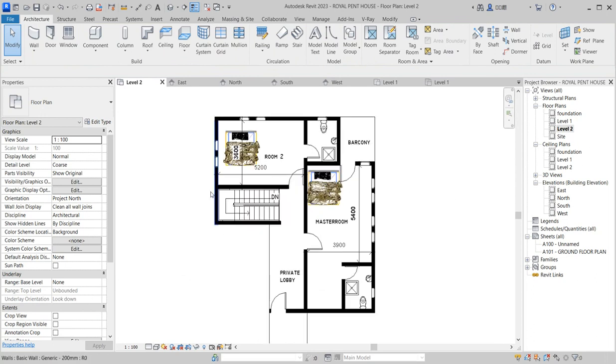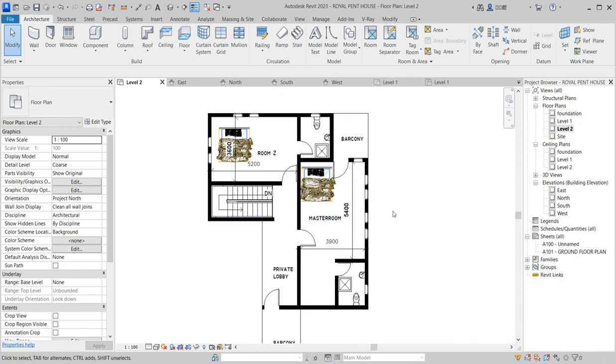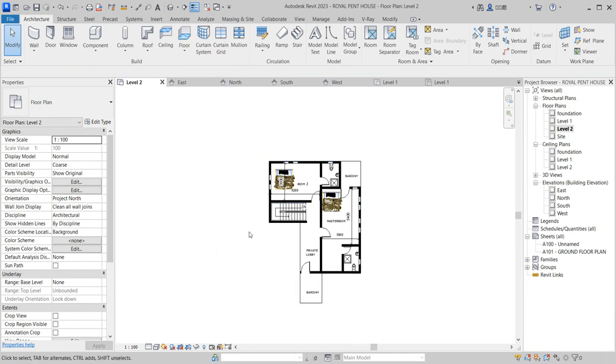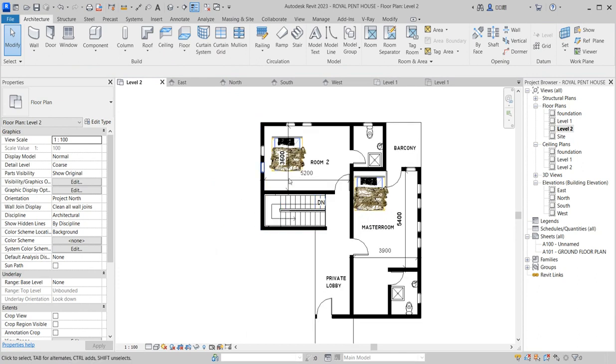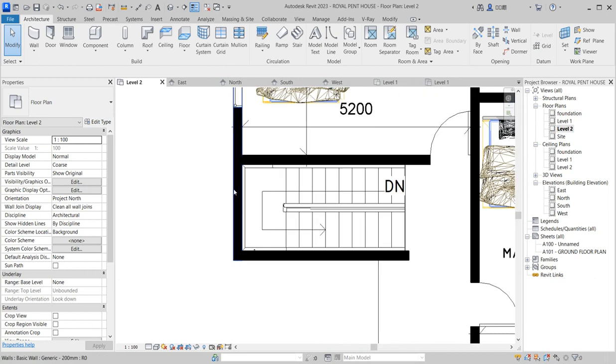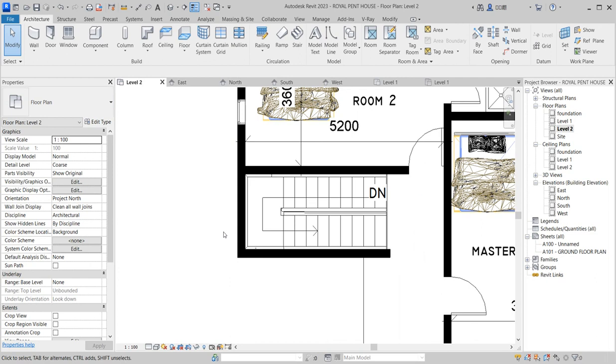So that is that. Now let us create the opening for this before we move to starting the elevations one after the other, by addressing what the elements of elevations are. So what we do here, I want to use a storefront wall on this one because I don't want to be creating an opening and start doing something.